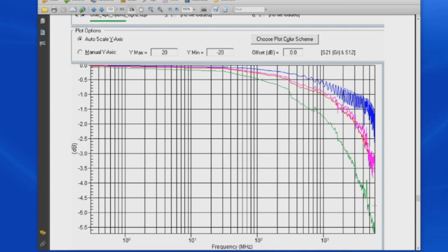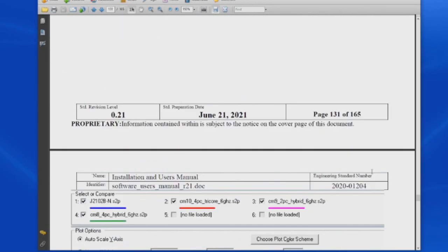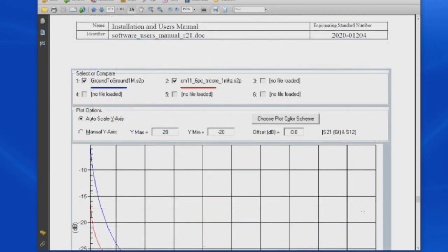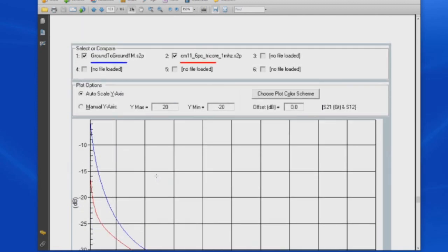You know, compare that with about 2.5 dB or so for the Pico test transformer. You can see transformers 9 and 10 have a much better return loss, but again, the common mode performance for those 2 transformers isn't as good. So based on everything I learned making these first 10 transformers, I made 1 more attempt, and that's this transformer here. And again, that's comparing it with the data that Brian had provided us.